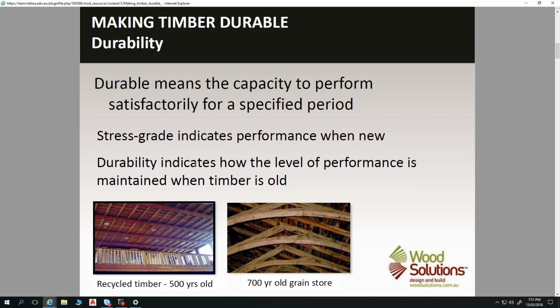Well, not necessarily, it may be in its natural form, but durability is the overriding classification for how we can use a piece of timber and how it's got to withstand certain elements and exposure. And that may be treated or untreated, whereas natural durability is just about the species of timber and how it naturally performs without any treatment on it.